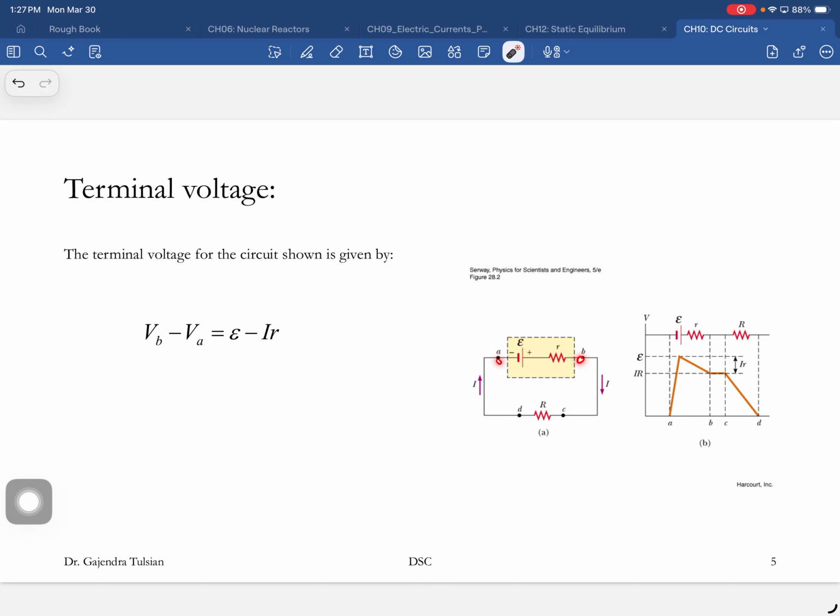And what this equation tells you is I squared R is the power delivered to the load. That's the power delivered to your toaster. What is this other term, I squared r? What is this little r? That's the battery's internal resistance. So that's the power dissipated inside the battery. That's the power wasted. That's what makes your batteries warm. So that's wasted energy.